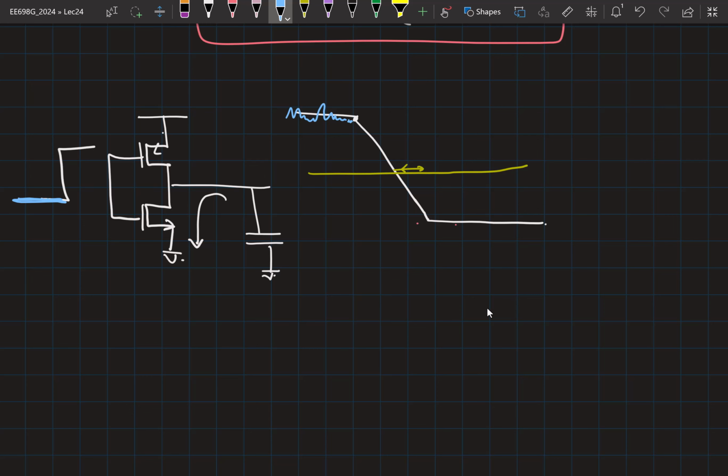Now, let's say at this edge, it got completely cut off. The starting point from which the voltage is dropping to zero depends on the noise from before. So, based on that, your waveform could either look like this, or if that noise was like this, it could look like this, etc. So that is also contributing to jitter.